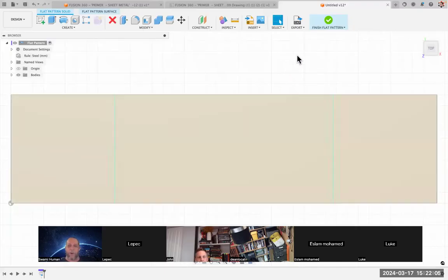And we are in a special mode, and we know that because much like the sketch mode, we have a finish button up here. Looks a lot like it. So we're in a special mode where we have the thing flattened out. And if we look over in the left on the tree, we have a folder for bodies. And we have another folder inside there, a group for the bend lines. And that's for our center lines and our extent lines.